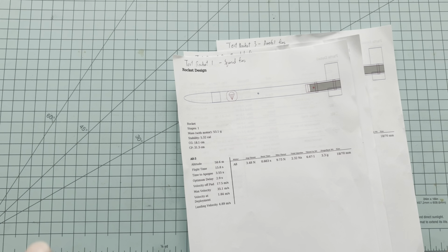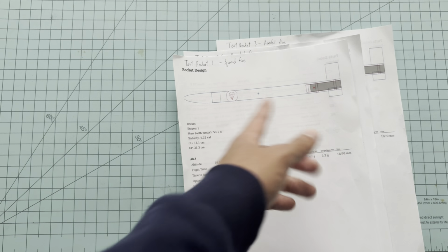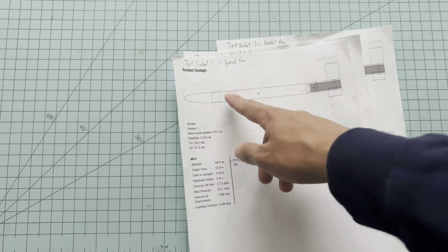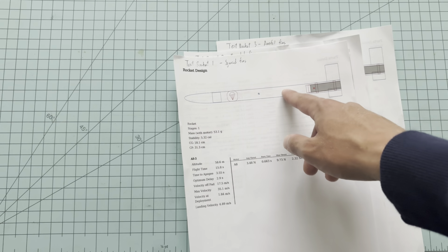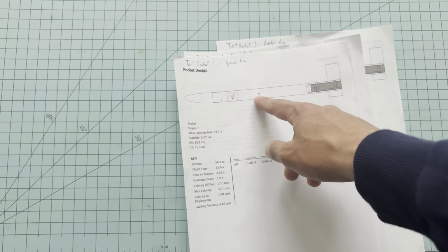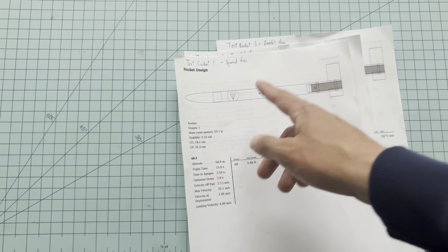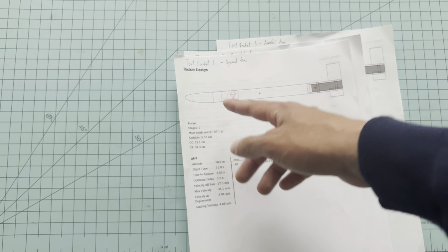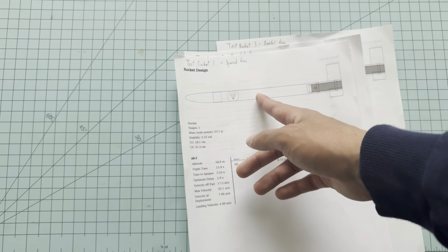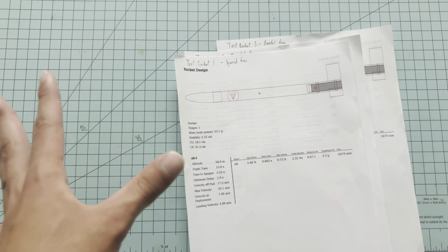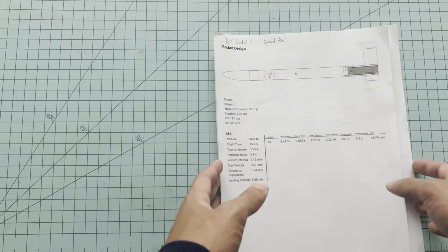Plus, I didn't include every component on the inside. The parachute will most likely gravitate towards the back of the rocket, which will push the center of gravity forward. The reason the center of gravity is so far ahead is simply because PLA 3D printed nose cones tend to weigh a lot. It brings the center of gravity forward, which can be beneficial, can't hurt. But besides that, that's the general thing.